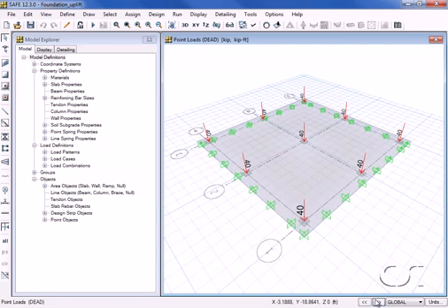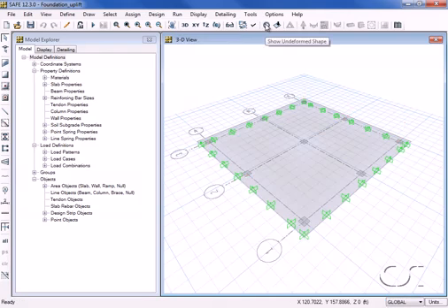The live load is 60 kips at each column, and the earthquake load is modeled as 10 kips up along the A grid line and 10 kips down in the C grid line, thus creating an overturning moment. For this analysis, we are ignoring the lateral load on the foundation.